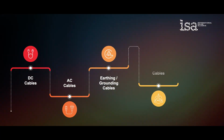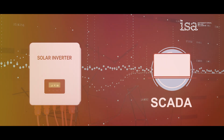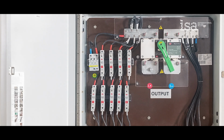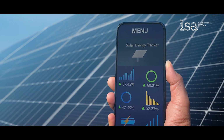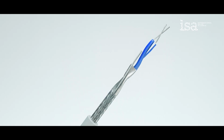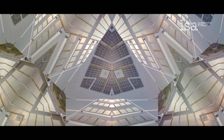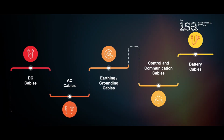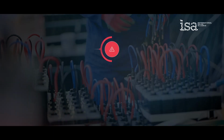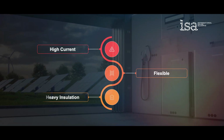Control and communication cables. These cables carry monitoring and control signals, not power. They ensure seamless operation of inverters, string combiners, trackers, weather stations, remote monitoring systems. Common types include shielded twisted pair RS485, fiber optic cables, control signals for trackers, battery cables used in off-grid and hybrid systems. Battery cables must handle high DC currents. They are flexible, thick, and have double insulation for safety.